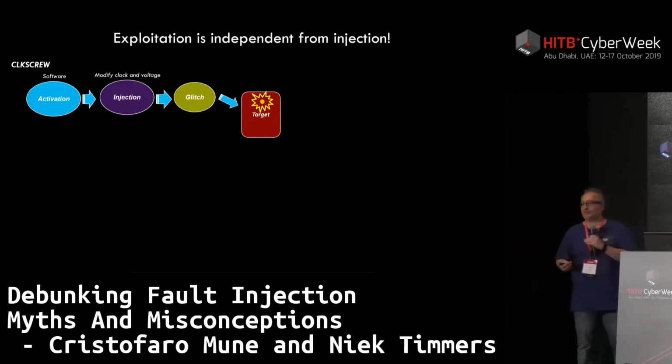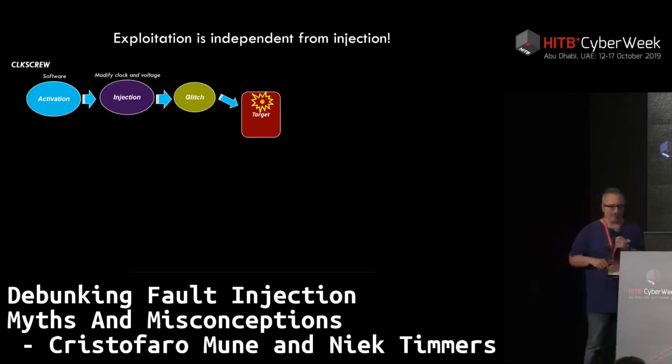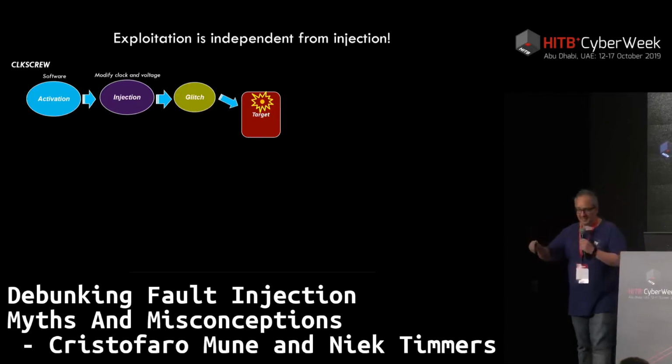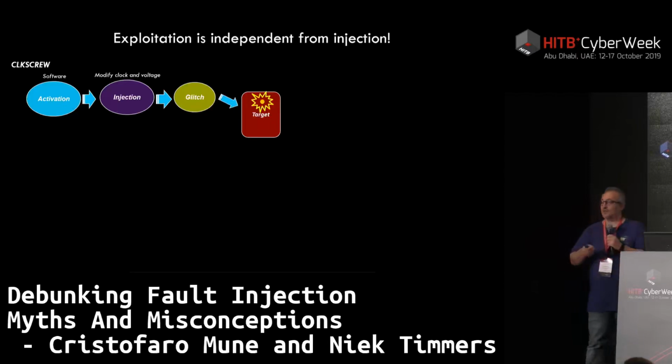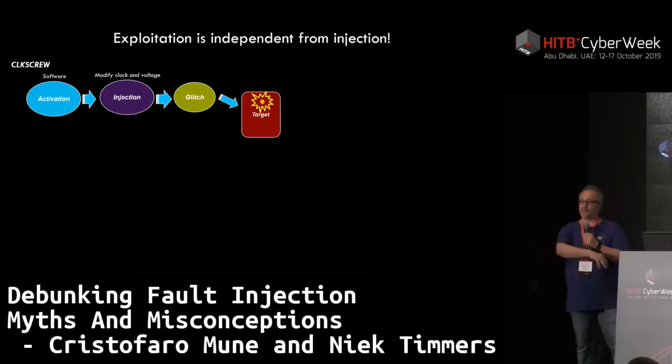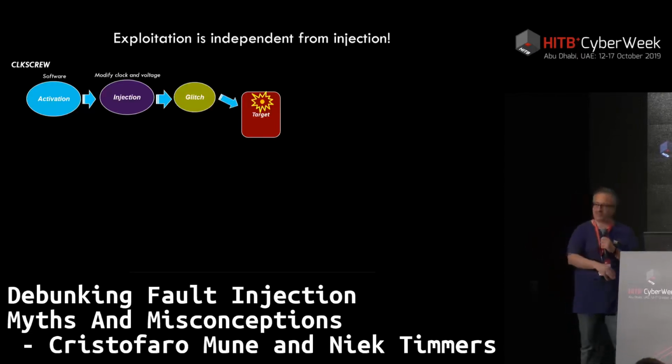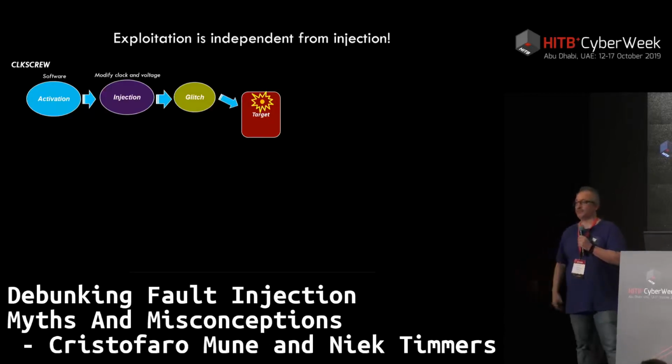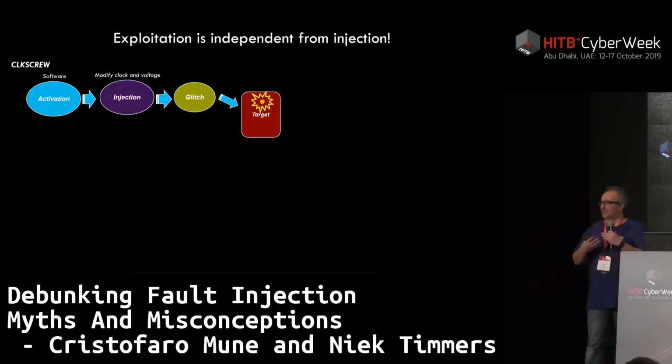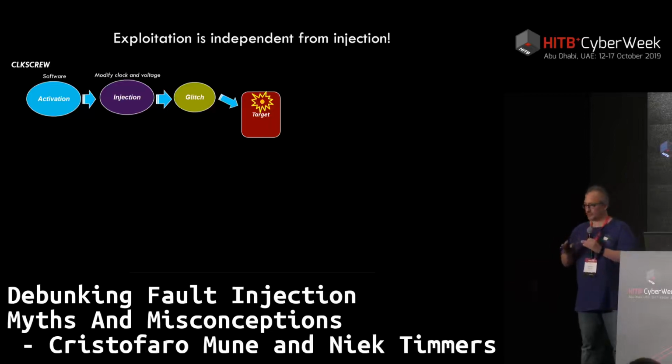And you can do that because there are IPs, there are registers of the DVFS, dynamic voltage and frequency scaling, which are needed for the kernel to say, hey, let's go into low power mode, let's consume less energy. When on mobile phones, we don't need to drain the battery, go to sleep, core, go down. In order to do so, there is something that needs to orchestrate the energy management, and DVFS are key points in mobile phones for doing so.